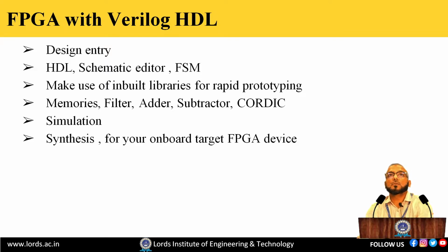So the main concept is how the design entry should be. A module is nothing but a black box entity, and we write a module with signals, wires, registers, input and output blocks, multiplexers, and synchronizing clocks. In the same flow, we create the source and write the module. Then in ISIM, the simulation environment, we write the test bench. Combining these two, we produce timing constraints. We write the timing files, do the synthesis and simulation, and then generate the report. This is how the list should go on.